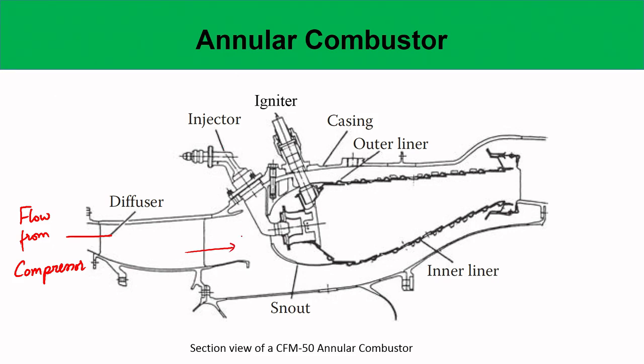So the air comes in here, and as you see here you have the injector. But before that the air essentially gets split into two parts. So it can come through here, and this is only the central section, so there is ample space for the air to enter into this region also, and then it recirculates and enters into this, and passes through these swirlers on which the atomizer injector is mounted.